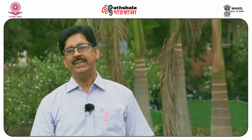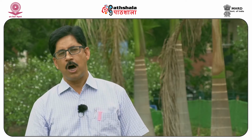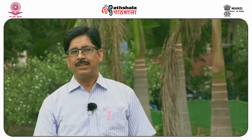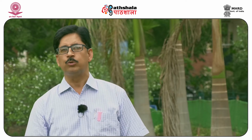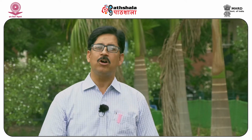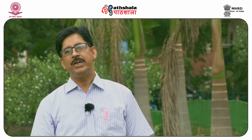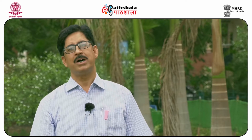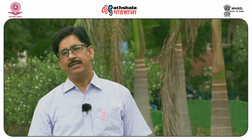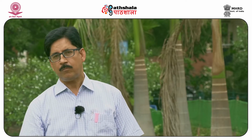How? By sealing these fractures through grouting, or by connecting the blocks through rock bolting, or if you have very large size blocks, then you can connect them through rock anchors. So, in this way you can improve the rock mass strength by strengthening the rock along the joint surface.